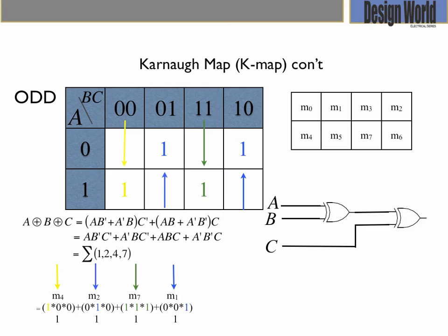As a consequence, the multiple variable exclusive OR operation is defined as an odd function. The odd function is identified from the minterms whose binary values have an odd number of ones. The complement of an odd function is an even function.